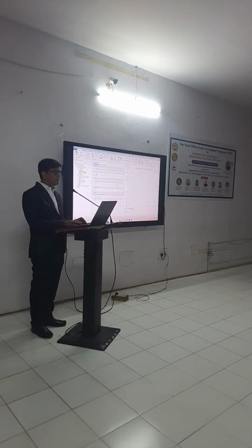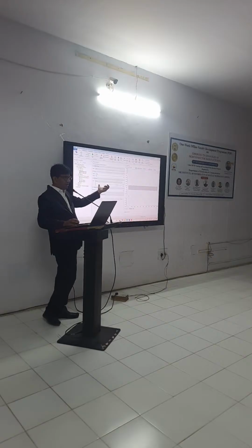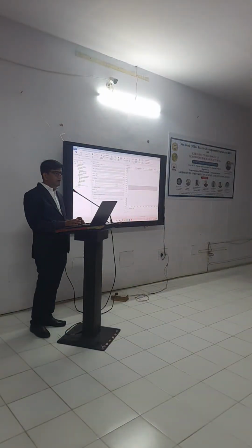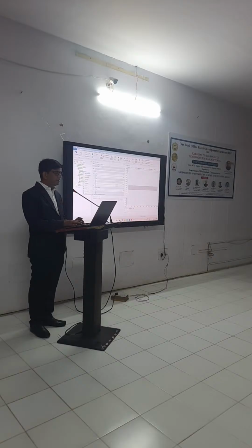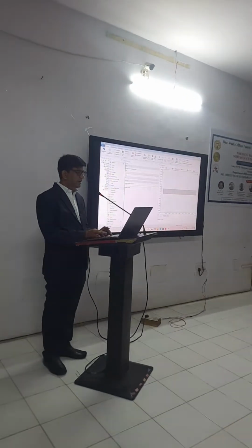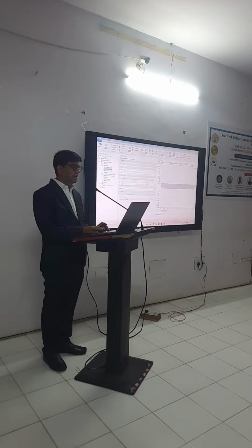Then I will select fill selected. So this is my PET substrate. So I have created my PET substrate. After that, what do I need? I need a bottom electrode. So for that bottom electrode, again, what will I do? I can either right click on this rectangle, or I can create a duplicate, or I can directly right click on geometry and again select rectangle.